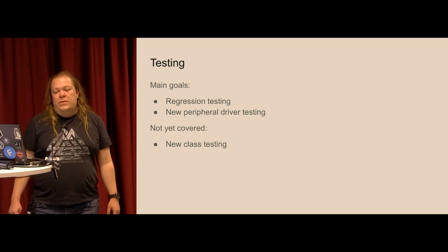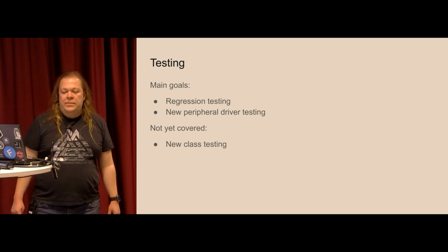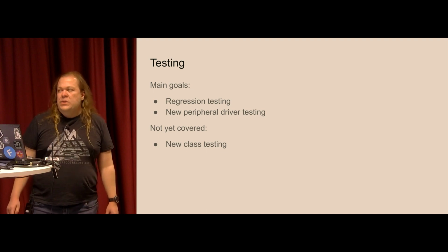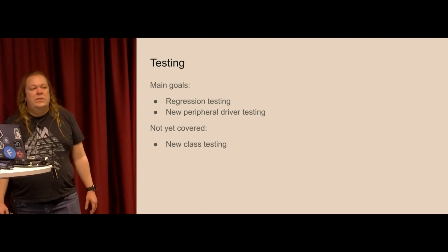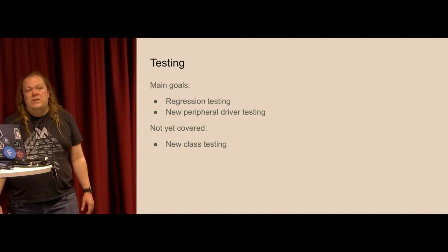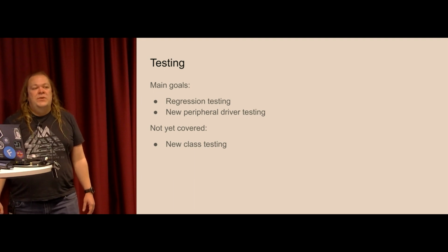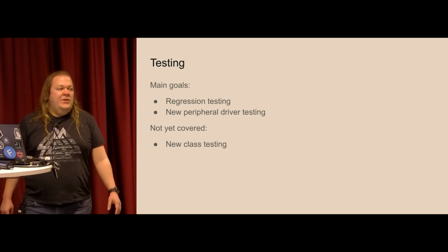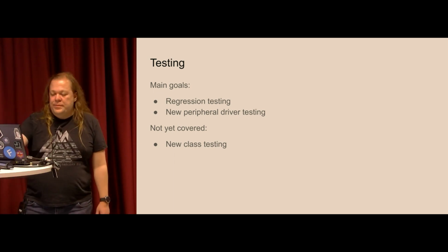And also for peripheral driver testing in general. So if you add some functionality to it. But what is not covered yet is class testing, because different classes are different and it's quite difficult to arrange some generic way of testing classes. So in general, I suppose that whoever implements a class is responsible for testing this class at least on one microcontroller to make sure that it works somehow.